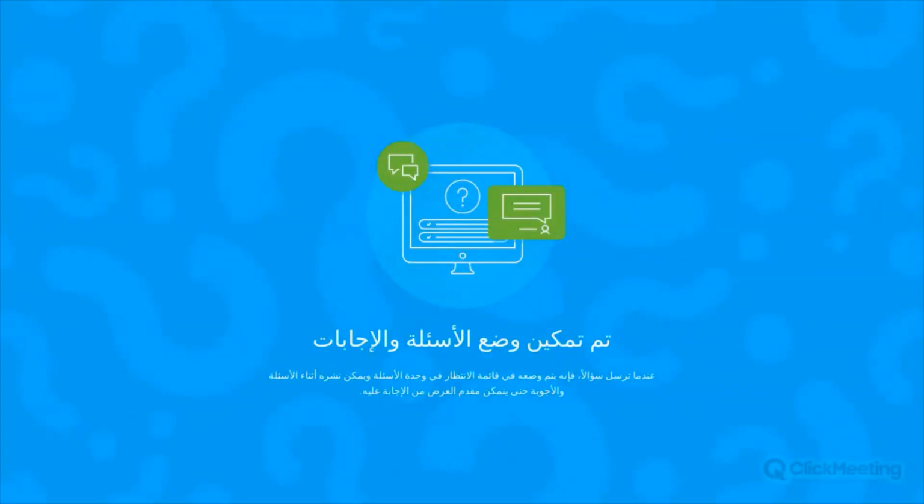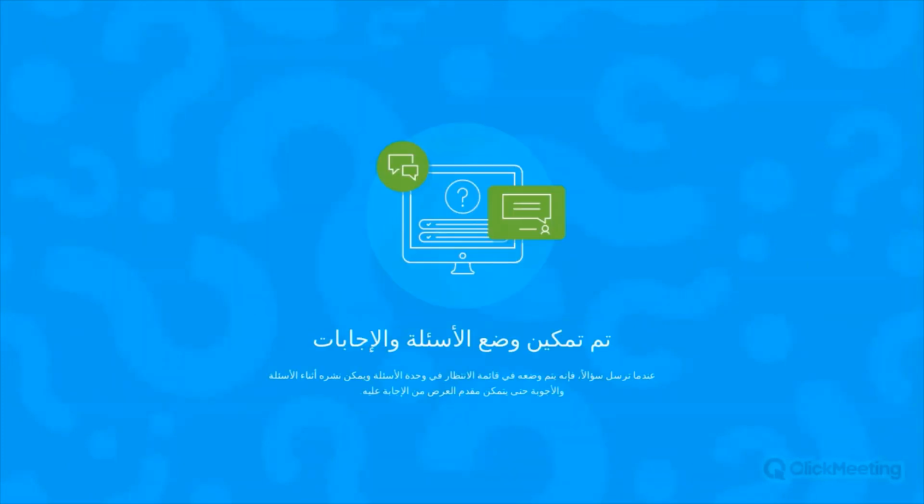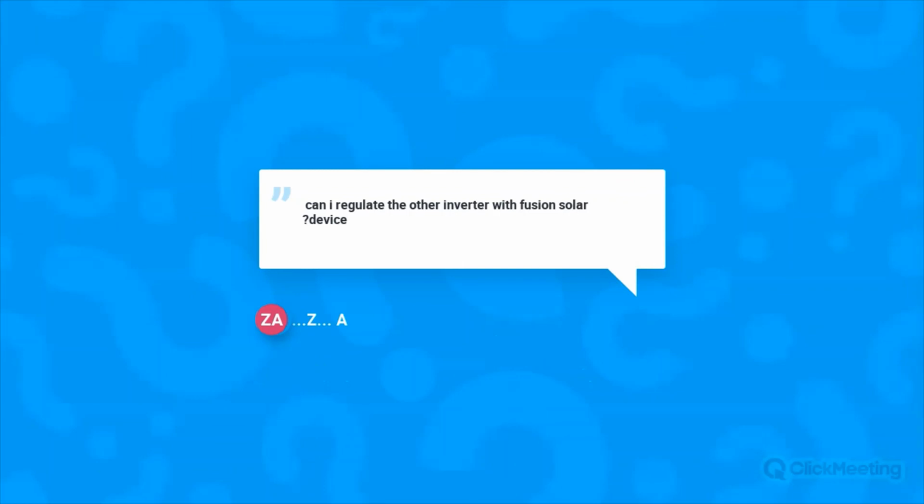Going back to the questions and answers. From Zishan, can I regulate the other inverters with FusionSolar device? Yes, you can. You can regulate the output of the other connected inverters from the master inverter using the power sensor and the dongle, or the power sensor and the smart logger. So you can control the other devices' output as well.